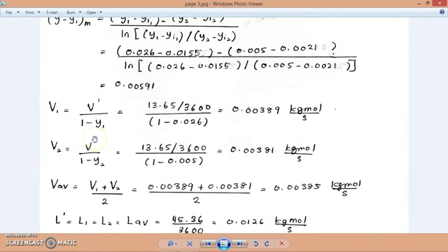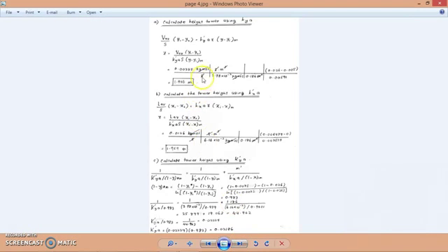So you have to standardize. You just divide by 3600 seconds, and then you will get the value for VAV, which is this value, and then substitute into the equation, then you will get the value of Z using the single mass transfer coefficient in the gas phase, which is 1.946 meter.